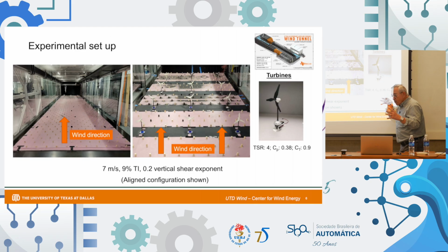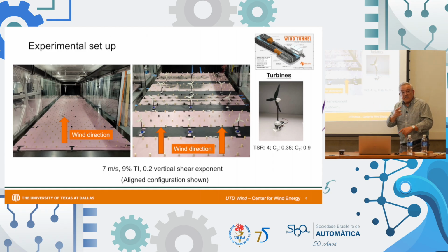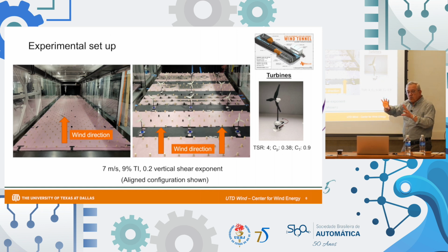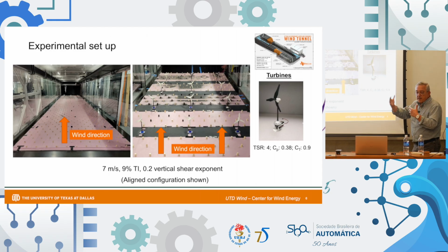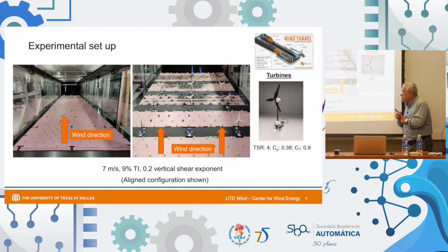When you scale down for an experiment in the wind tunnel, it's not just about making things smaller. It's not just about making your toy car. You need to scale down the aeroelastic properties, the aerodynamic properties of the blades, and so on. So for these machines, the aerodynamics is close to what needs to be, but the aeroelasticity is not there. Aeroelasticity is the fluid structure interaction in order to understand vibrations. But I have another set of experiments that will solve that.